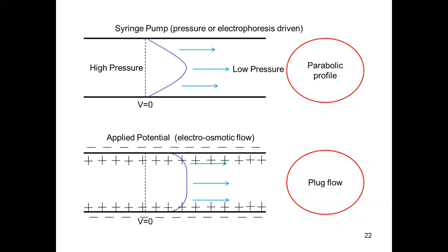But when we look at the syringe flow in the energy diagram above, we can see that the drag on the walls makes the pressure in the center lower, and that pushes the gradient to that level. So we're going to have a strong flow in the middle, and then drag on the sidewalls. That actually looks like the electroosmotic flow too. The ions are going to be dragging the material, but the sidewalls are going to have resistance as drag. So that's called more of a plug flow.